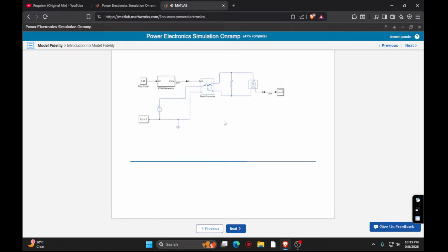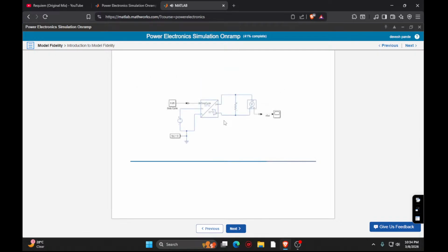In fact, the buck converter that you modeled in the previous activity included a common approximation, modeling the switch using piecewise linear equations rather than capturing the full nonlinear behavior of each switch event. By choosing other parameters or blocks, you can also choose coarser representations, such as averaging the PWM behavior, or ignoring the circuit components entirely and modeling a fully idealized DC-DC conversion.